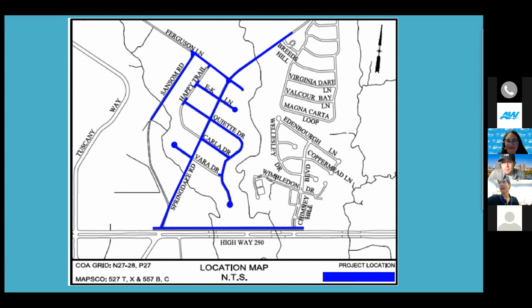The system pressures on EK Lane and all the surrounding streets are going to be quite high. So it sounds like to me that's a PRV setting, maybe it's too low. Perhaps, Miss England, if you have a plumber that you've worked with in the past, it sounds like they might need to adjust that PRV.